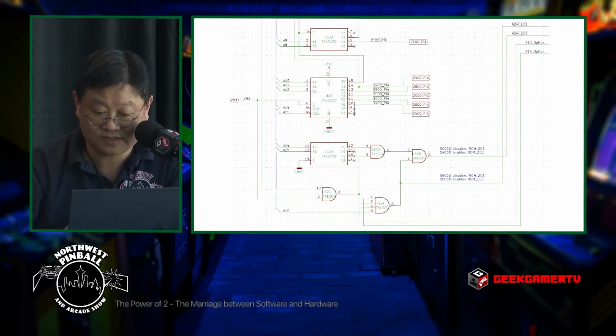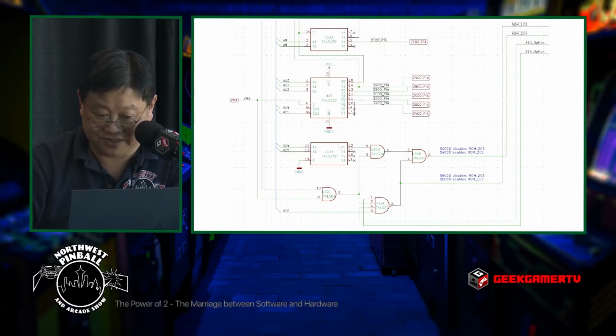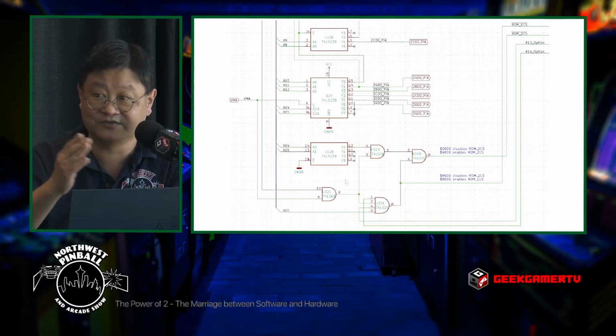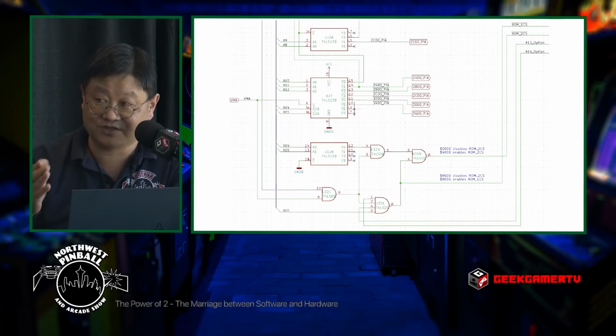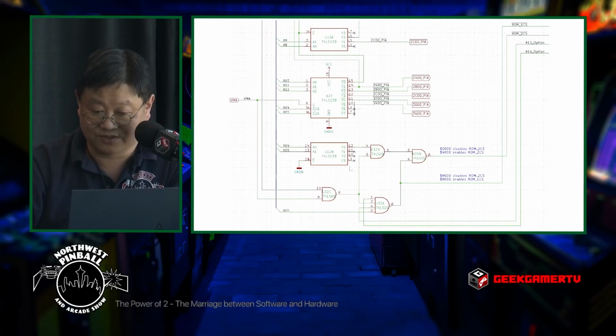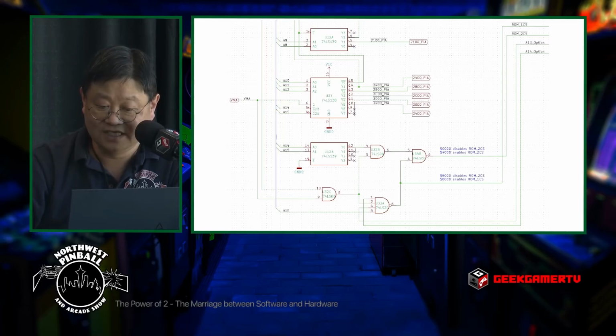So what this chip is doing is it's looking specifically for a 0, 0 configuration because it's ignoring everything else. It says 0, 1, I don't care, 1, 0, I don't care, 1, 1, it's only looking for 0, 0, which corresponds to that further decode between 0 and 4000. So what happens here? This signal comes out as 0.